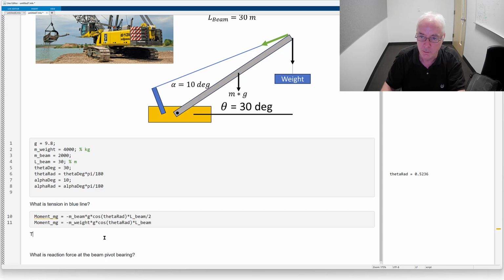And that the force will, in this case, the perpendicularity, well, that's going to be kind of the opposite segment length according to the location of the angle that's been provided to us, which is 10 degrees. So anyways, it will be times sine of alpha rad. Okay, and its moment arm will be L, the length of the beam as well.